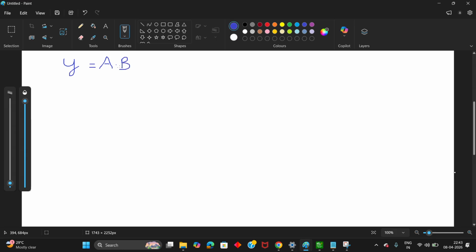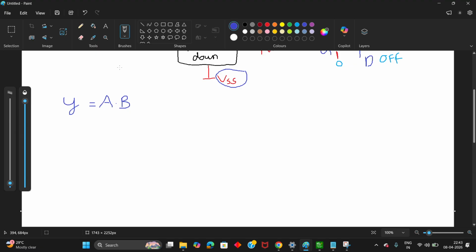Now if you look at this expression, it does not have a whole complement, so it is difficult to write the circuit. I'm not saying we can't write it, it is just difficult. Okay, so if your boolean expression does not have the whole complement, the first step is to give two whole complements.